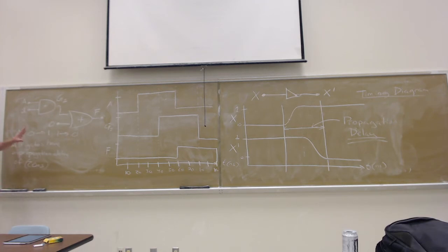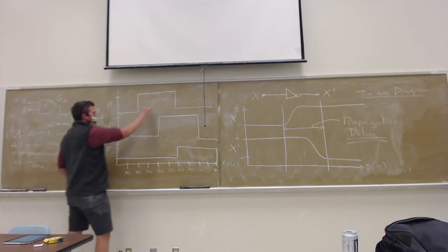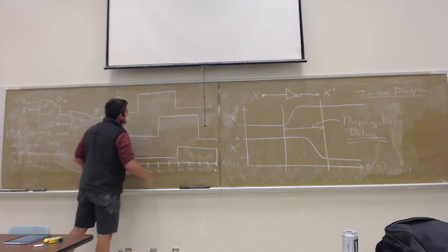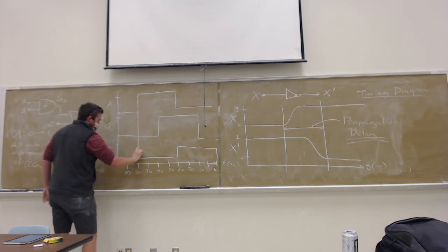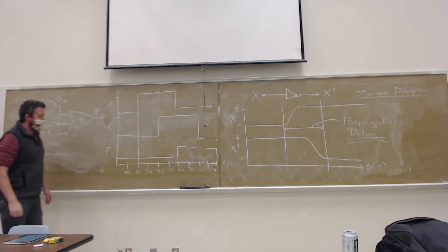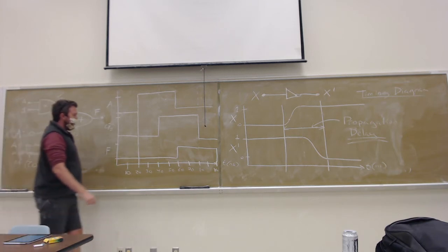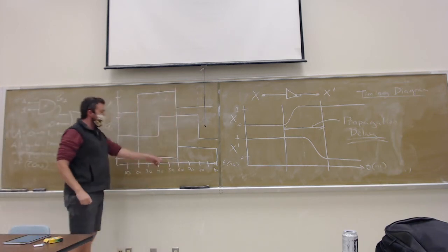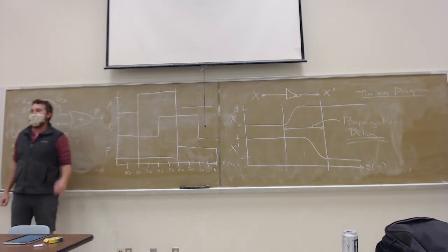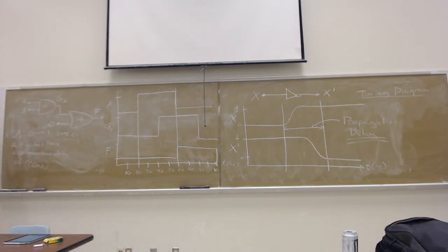So the important thing here is there are two things to note. Notice that all of the outputs sort of lag behind each other. And for the circuit as a whole, we switched it at 20 nanoseconds, but we didn't actually get the effect that we were looking for until 60 nanoseconds. There was a 40 nanosecond lag between when we hit it with the input and we got our corresponding output.